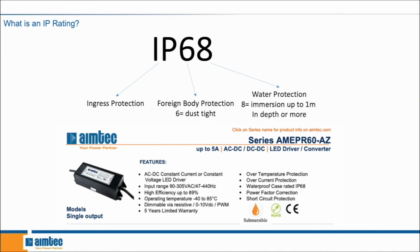Now we can talk about what an IP rating is, especially when it comes to LED drivers. IP rating talks about ingress protection. That's what IP stands for in the word IP rating. And some of Aimtec's LED drivers are IP68. The first digit talks about foreign body protection, and level 6 is considered to be dust tight. The second digit of the IP rating is water protection. And what 8 signifies is immersion up to 1 meter in depth or more.